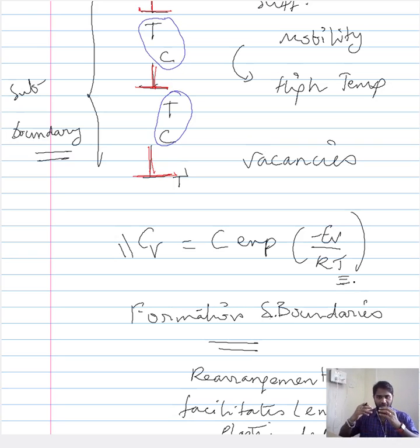We saw that only when you have a sufficient amount of temperature do you introduce sufficient mobility to dislocations, and sufficient vacancies for the dislocations to climb. So you have a rearrangement of the dislocations, thereby allowing enough space or reducing the overall dislocation density. Supposing your temperature is further increased or decreased, now you can understand how it would affect the different stages of creep.